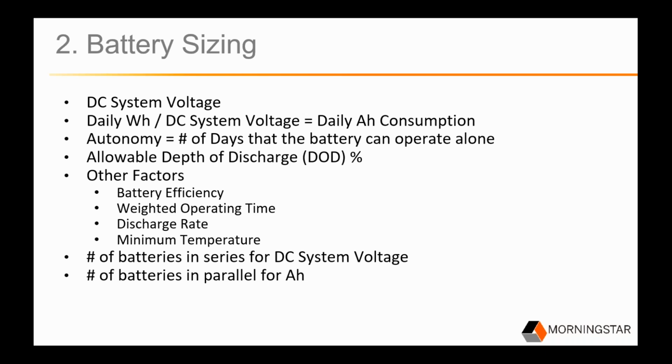Once you've selected a battery model and determined the battery bank voltage and amp hour requirements, the battery bank size will be determined. A battery bank will consist of batteries connected in series to meet the system voltage and connections in parallel to meet the amp hour requirements.